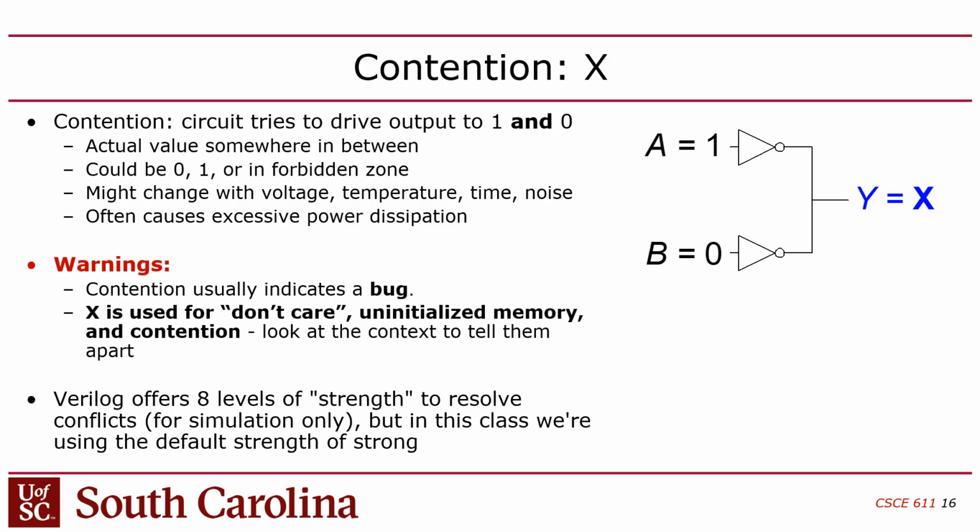contention. When you have a logic circuit that has an output, that output can't be shorted to the outputs of any other logic circuits. The rule is that if you have a wire, you can only drive that wire, and when I say drive, I mean set that wire, with one output. It can be connected to as many inputs as you want, but you can only have one output driving a net. Does that make sense?